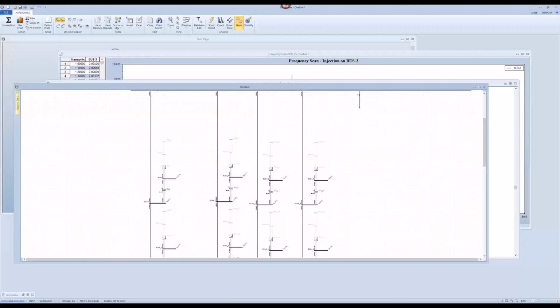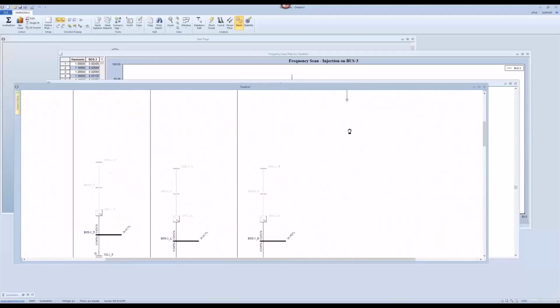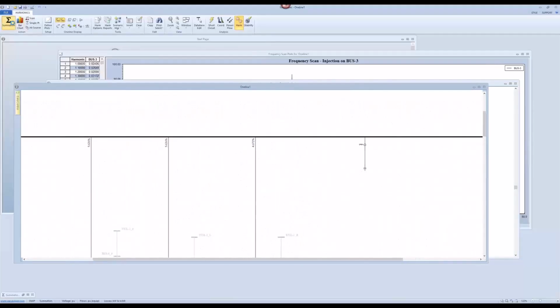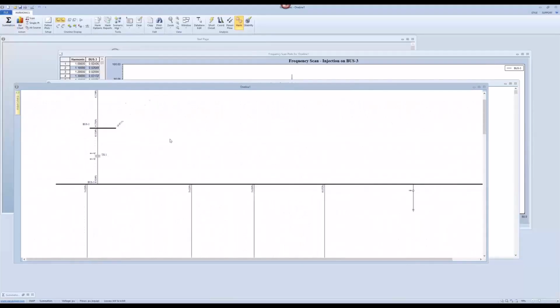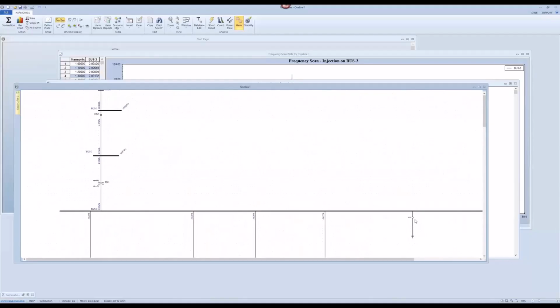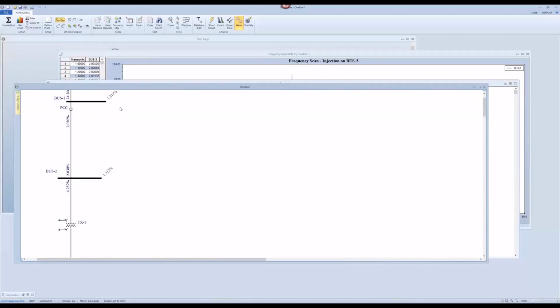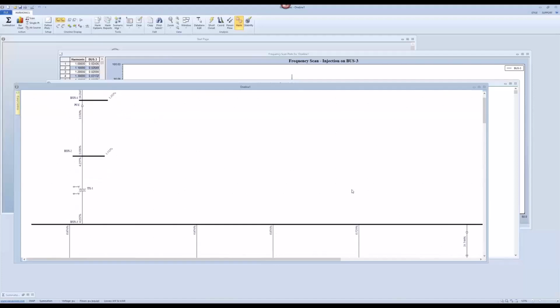What is the THD at the TCC with the 10 megavar cap bank? I think THD was 10% without the cap bank, and I would like to see the THD change. Yeah, sure. So let's go to harmonics summation. The level of 10% is without the capacitor. With it, you will reduce it significantly to 1.311. Here we go. So possibly you filtered out some of those harmonics.